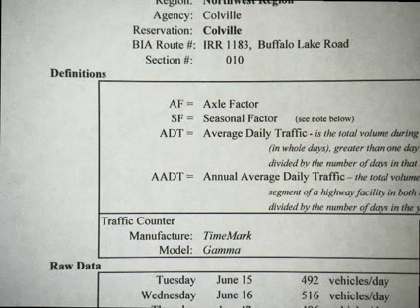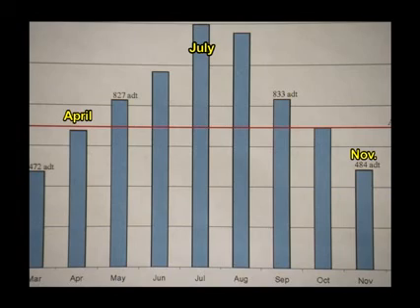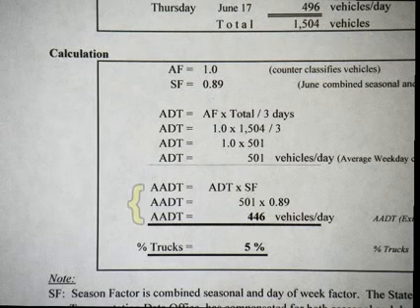To create accurate traffic count reports, you must use the seasonal factors, which account for historic seasonally high and seasonally low traffic days. If you don't adjust your data by multiplying these seasonal factors for the date of your count, the results will not be accurate.